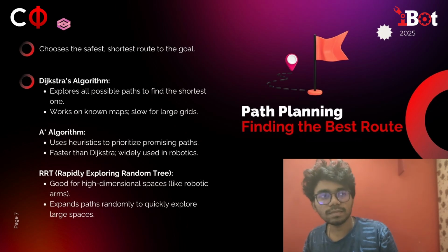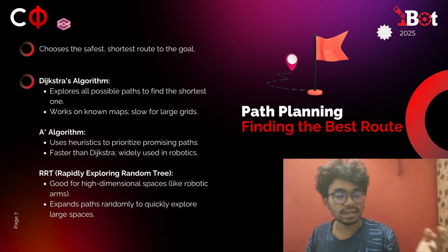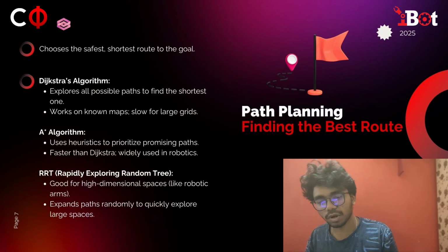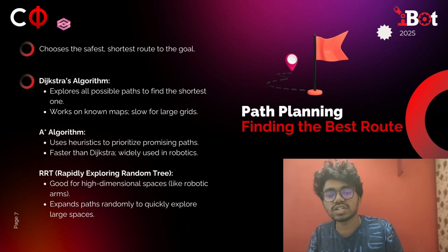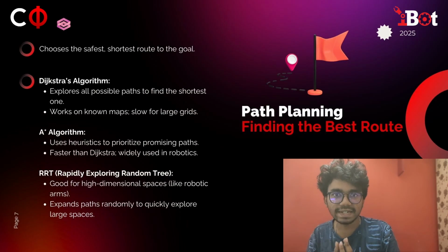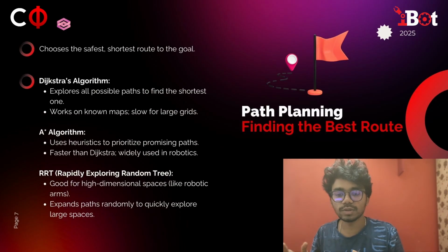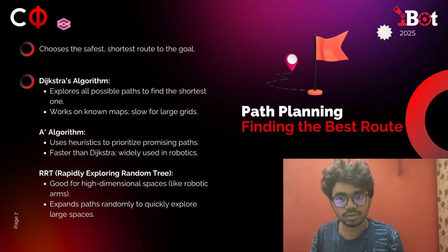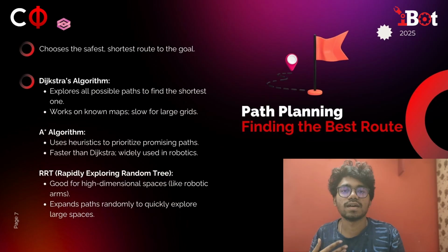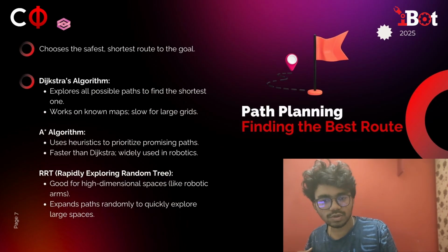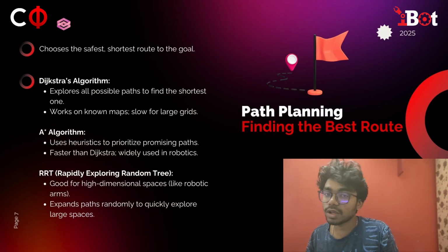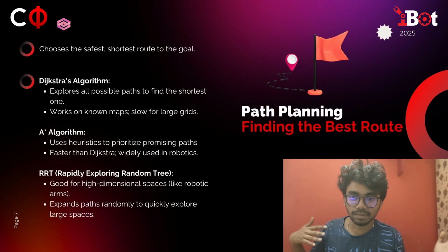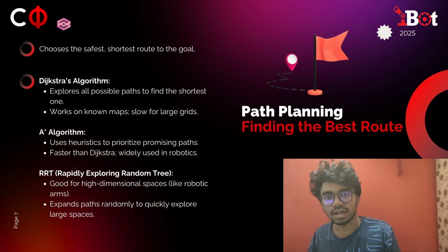The bug algorithm has quite a few modifications, and left follower also has a lot of modifications of what to do. Like if there is a loop, they add a condition: if you got to the same point three times or more, then you need to change, go right to explore more paths. Basically, there are versions of left follower which will not get stuck, but they are not as optimized as other planning algorithms like A star, Dijkstra and RRT. So each has its own use.